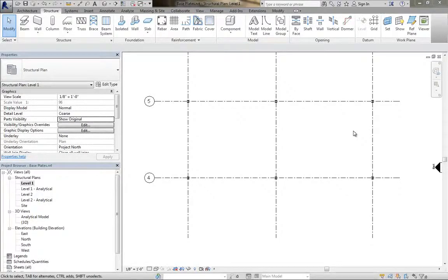Okay, it was asked whether we could have the column base plates be associated with the bottom of the column versus a work plane in Revit. It largely depends on the column base plate family, but as long as that column base plate family can be face hosted, yes, you can have that association in Revit. So if your column base essentially moves up or down, your design's still in flux, your column base plate will move along with the bottom of that column. And that's where I'd recommend using that if your design's still in flux.